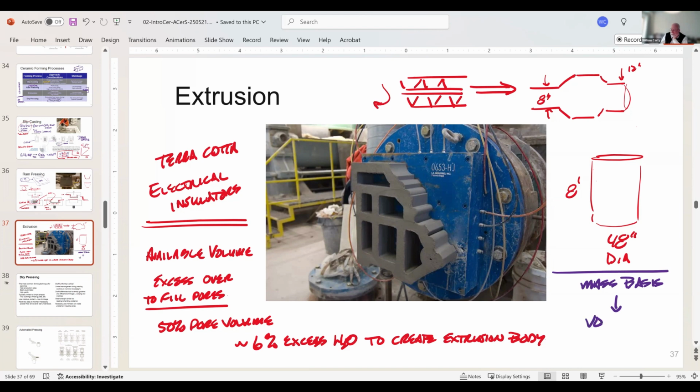And here's a problem. If I'm alumina, I'm at 4 grams per cubic centimeter, and water is 1. So 1% by weight is 4% by volume. So I have to correct for that. That's why this becomes important, because if I was close and I add a percent water, I just leaped over my window. This is 6 to 8% excess water is what it's supposed to be. But the idea is that we need to be thinking about this on a volume basis.